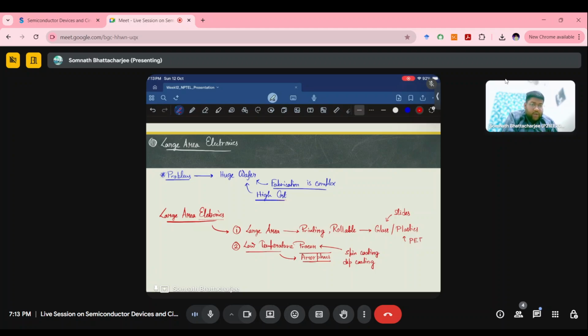Spin coating is when you are dropping a simple liquid on top of a spinning substrate, and the substrate spins, and based on that, the liquid is flowed over the surface, and there is a very smooth film, and based on that we are depositing each of the layers. Dip coating is very easy, it's just dipping into a liquid or something of that kind.